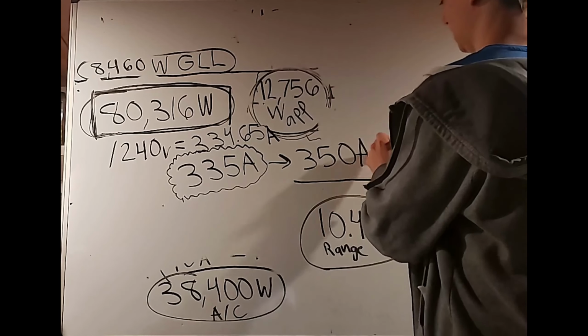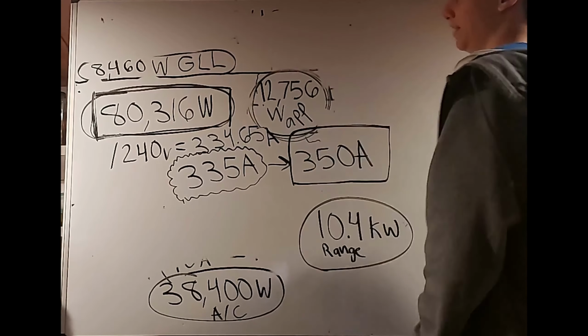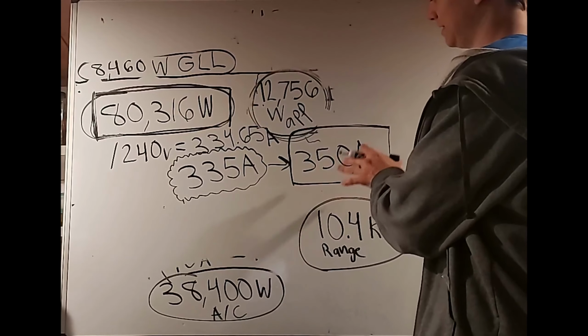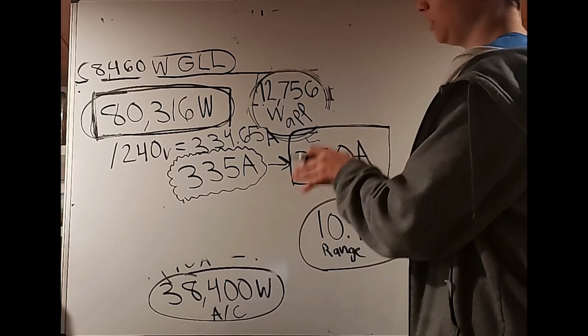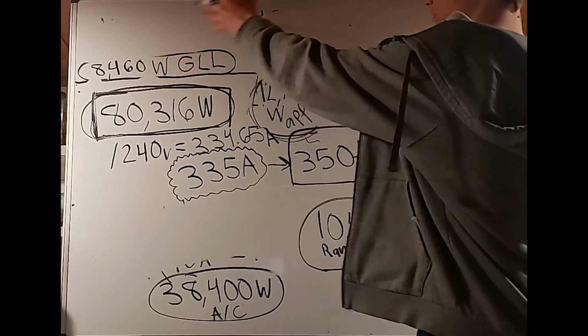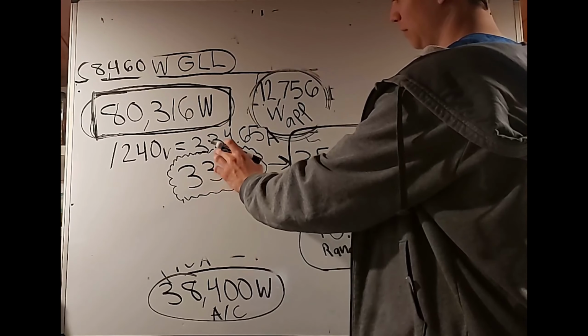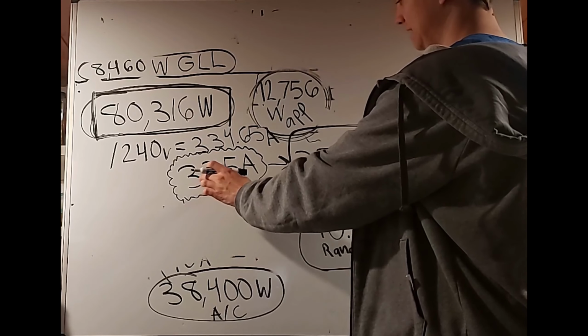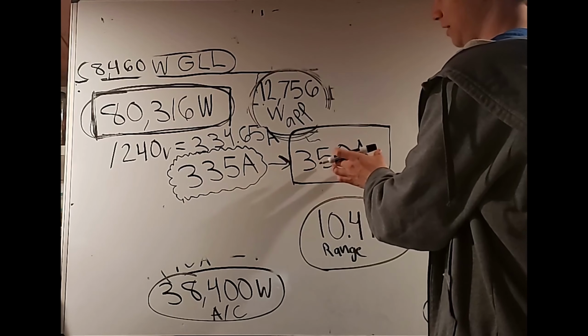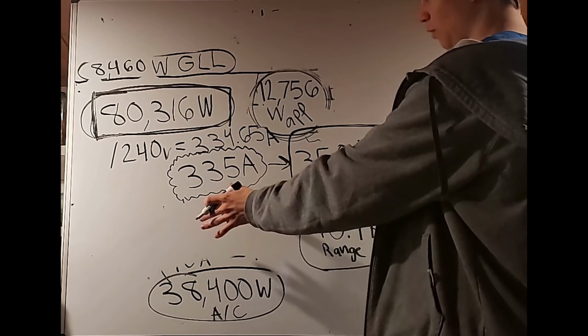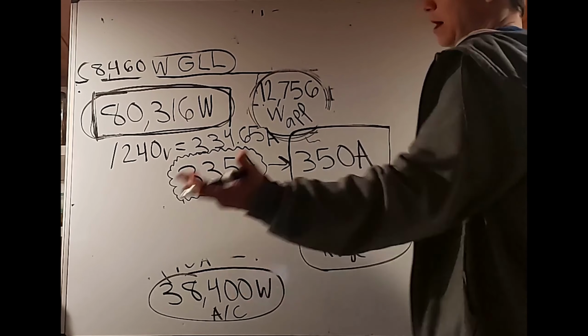Okay, the reason why we're doing this, because if you think about it, the breaker is telling us how many amps we can put on our wire. And if we just figured out our total demanded load for our duplex, and this is our total amount of amps, then why would it make sense to size up the breaker telling us to put more power? You might say, well, logically, we'll round up so you have more power.